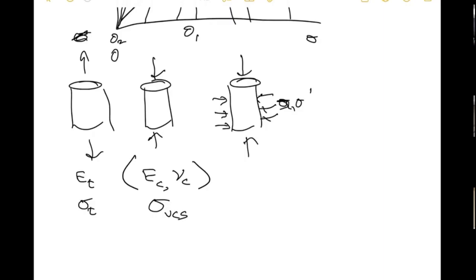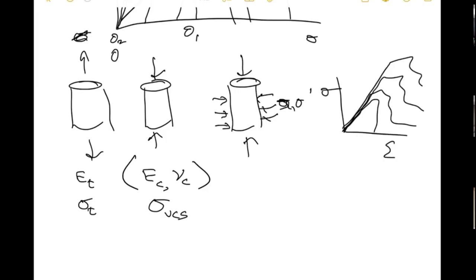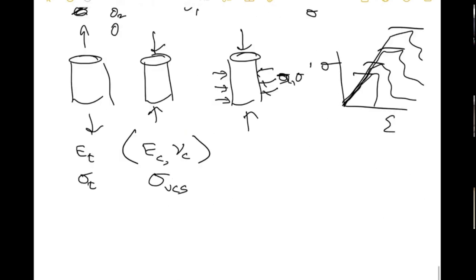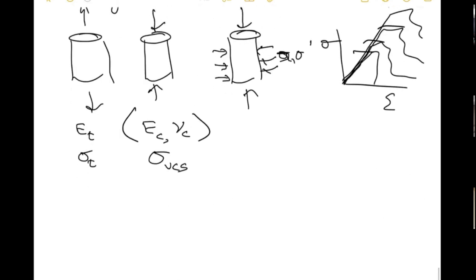And now based on all of that, remember, you get stress strain, goes like this. You take these peak values, you go to that Mohr-Coulomb thing here, you get a slope and you call that a friction angle. And so from this, you get friction angle.